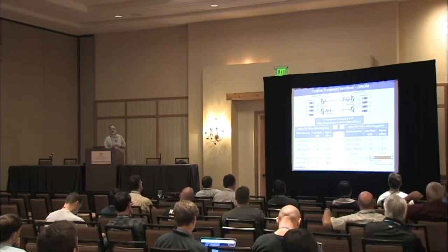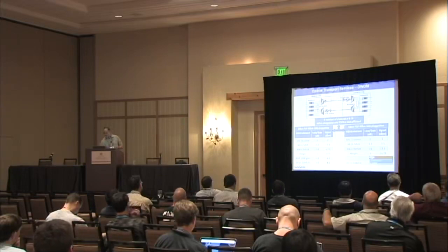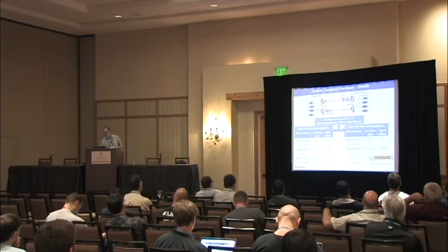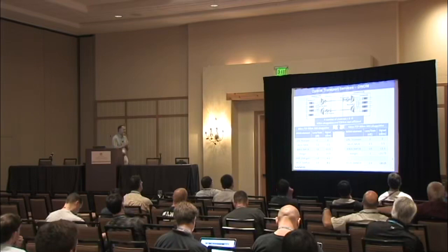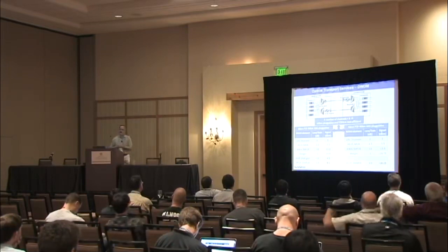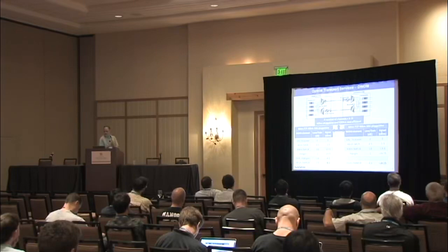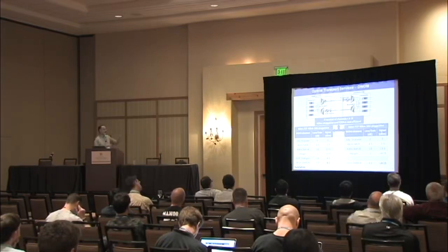For 40 kilometer optics, I'm just at the edge of my sensitivity of minus 15, including the dispersion penalty. So I need to amplify. I added an amplifier of 10 dB, and that brings my signal back to life at minus 4.5. The 40 channel Demux gets my signal back to minus 8 dBm, nicely within the active range of the transceiver.